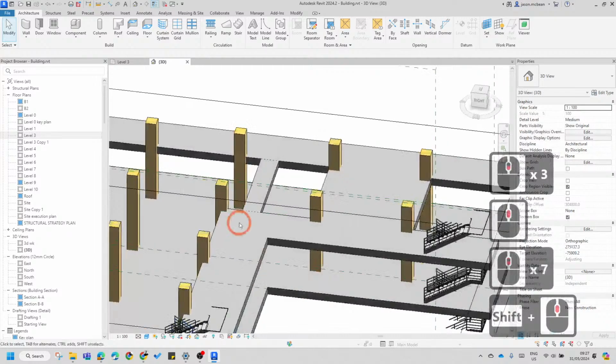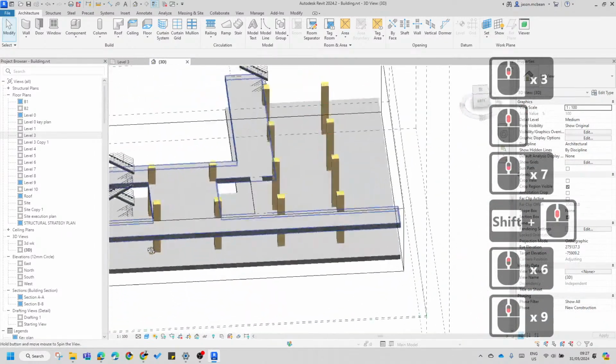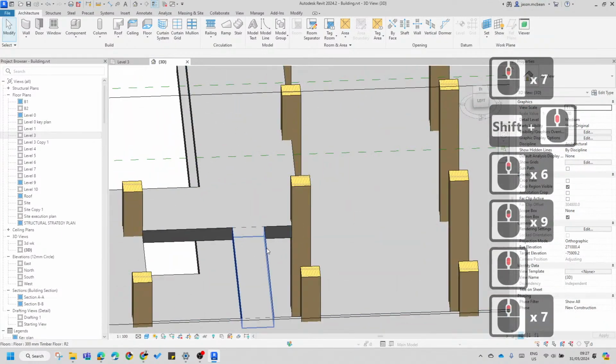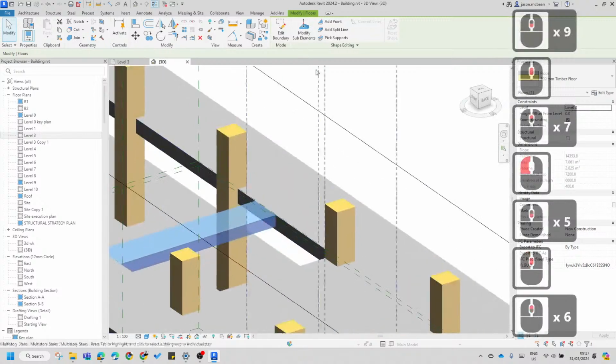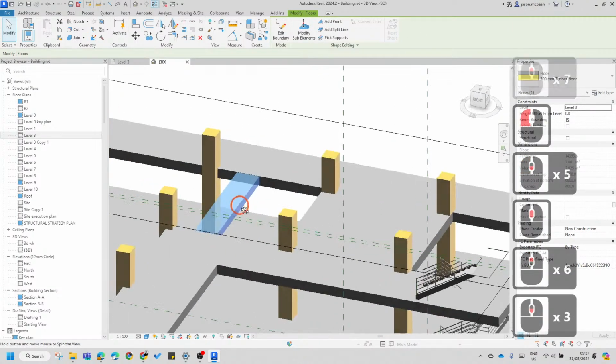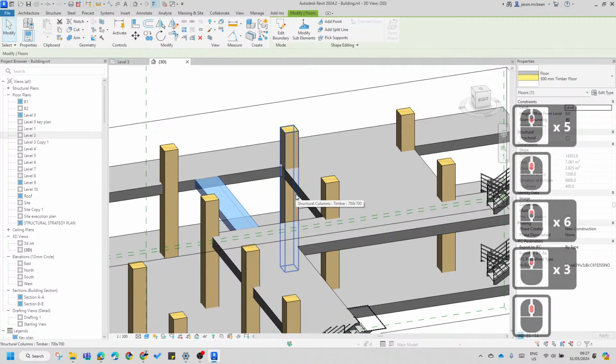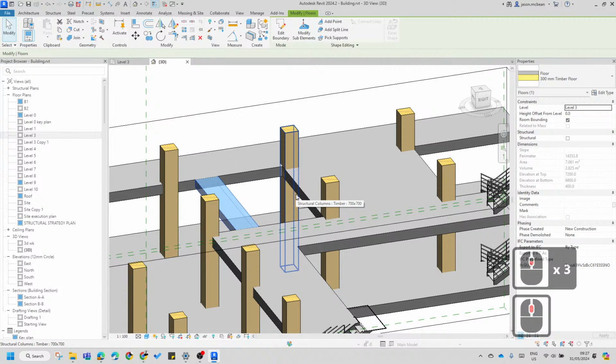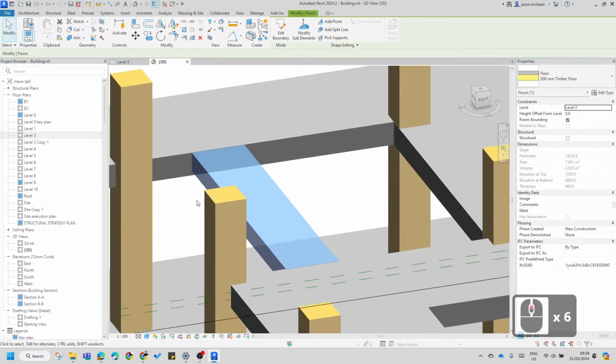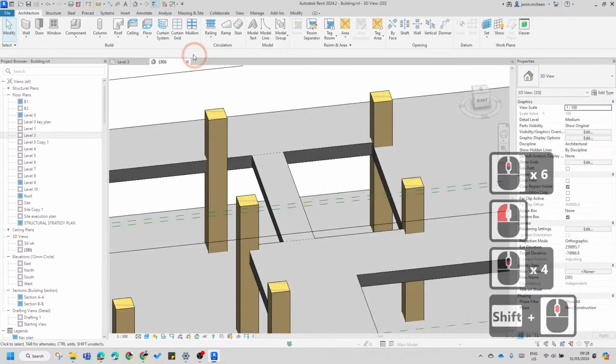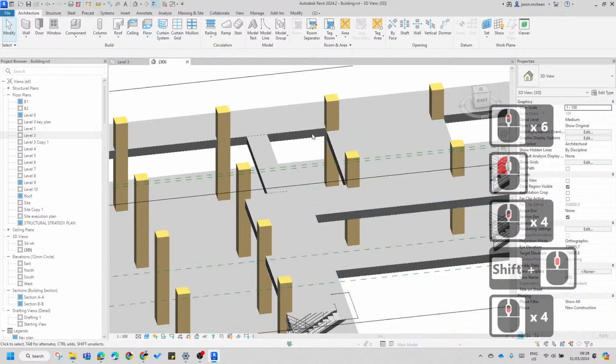So if you cut a section through here, the issue I'm having is that the bridges are made of steel and timber. It's not really concrete. Then you just change the material to suit. You literally change it so it'll have a steel sub base. That becomes steel, but you might still have steel I-beams on the edges and then the concrete. That gets a little different. Then you might have to start using structural steel systems.